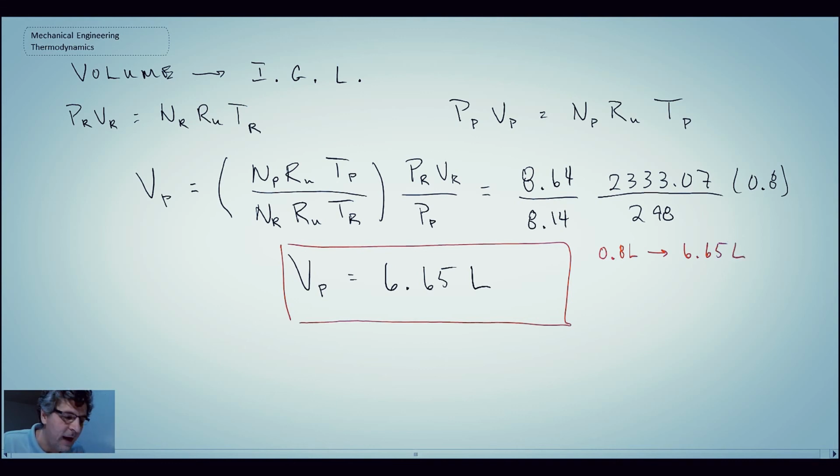to freely expand. So those are two demonstrations of adiabatic flame temperature for fixed mass, either a constant volume or a constant pressure process. And you can see it's a little bit complex because you do not know the temperature of your products, and consequently what you need to do is guess values. And then once you've guessed them, you compare them to how things turn out, and you do interpolation in order to get the final adiabatic flame temperature.